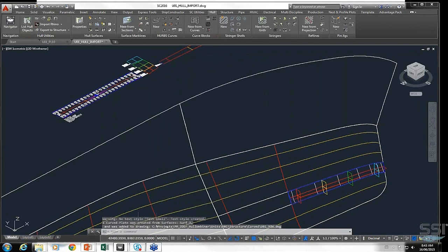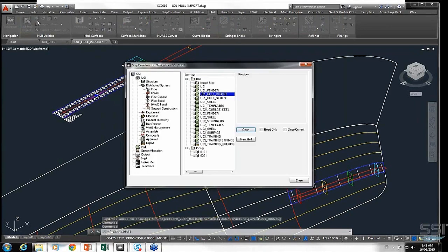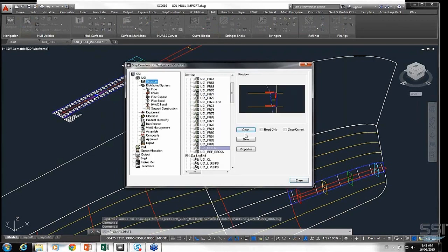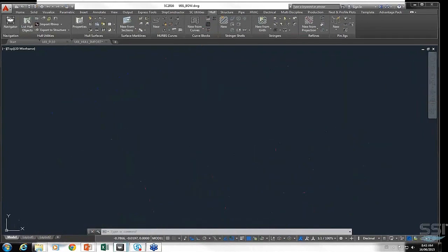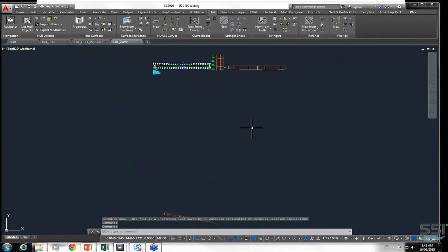One curved plate was created from surface, and we can now go and open that drawing. I'll head down to it, open it up. And now we can see these: the curved plate, the expanded plate, and the forming templates. You can see that the curved plate, expanded plate, forming templates are all loaded into the structure drawing. And these are linked to the curved surface and hull.